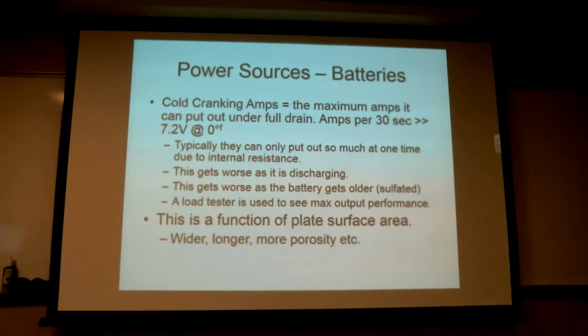Right? Now, what I will tell you is that scale is sort of stupid on the voltmeter. What happens with a truly shorted cell is you go one click, boom. It drops immediately, very, very quickly, because one or more cells are shorted. They can't put out anything. So you immediately go from a vague 12.5 volts down to 8 volts or some other value. It's going to drop really, really quickly.